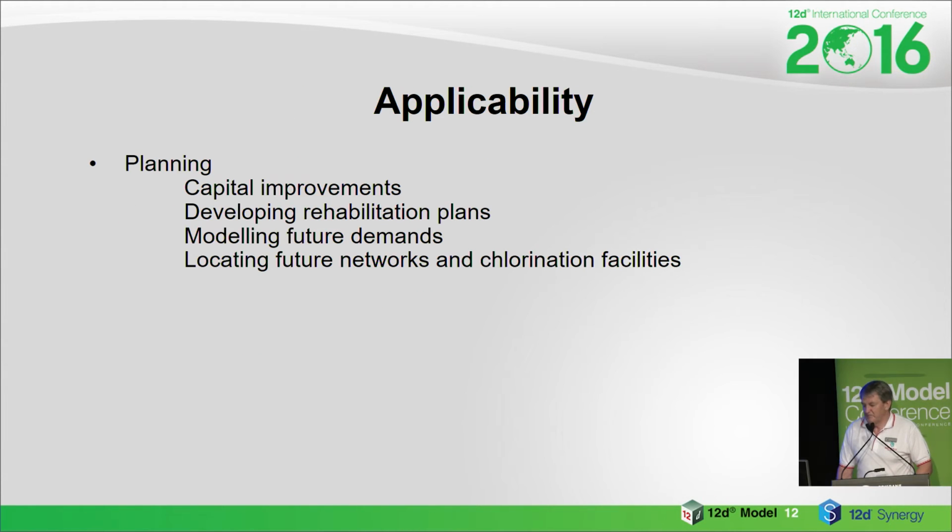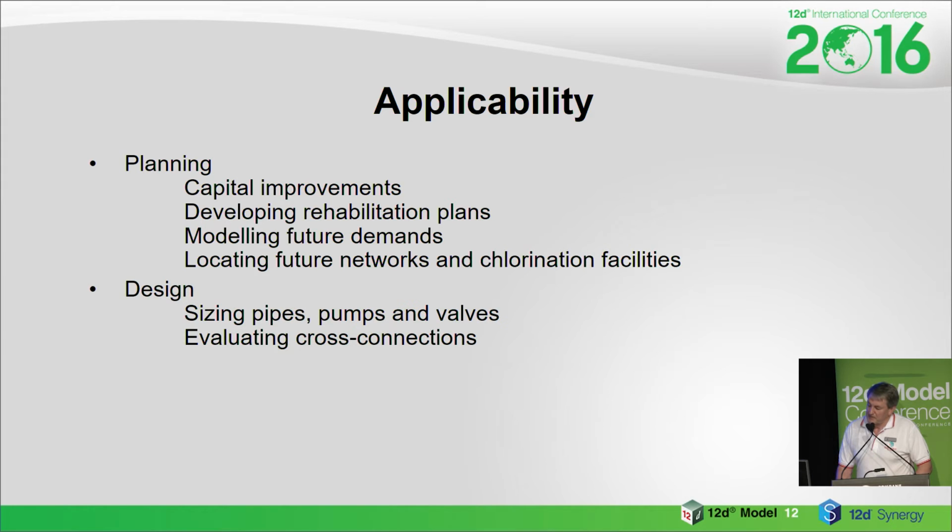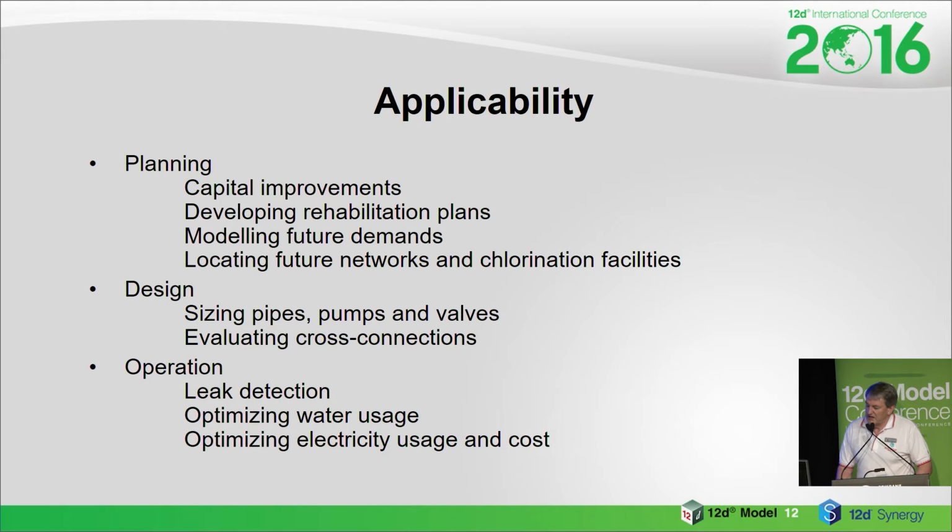It's applicable for planning, so for capital improvements or rehab plans and so on. Can be used for design to evaluate cross connections, to size pumps and valves and so on. Can be used for operations, for leak detection or for optimising electricity usage, so you can work out the cost of running pumps. Or asset management and ADAC, and you'll probably hear something about ADAC at some stage during this conference.